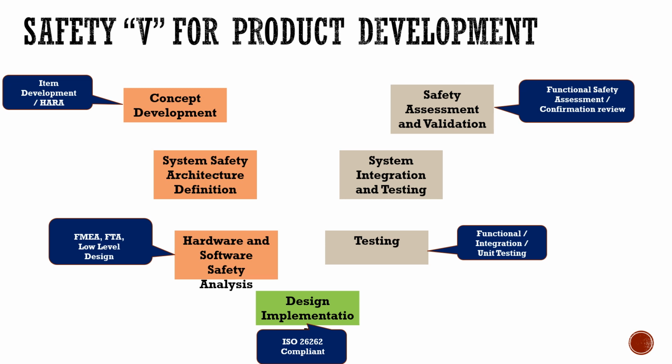So what is the difference between other automotive standards and this functional safety? In functional safety, there are 4 different levels of ASILs. Based on the ASIL levels, we have to define our product. Some of the activities are mandated and some are highly recommended, depending on the ASIL level.